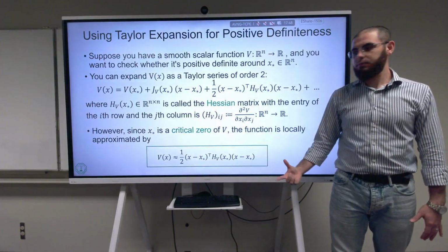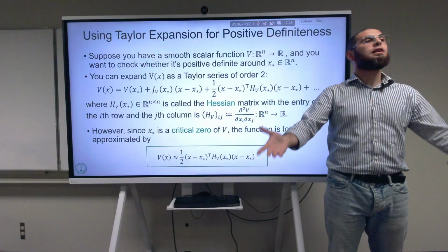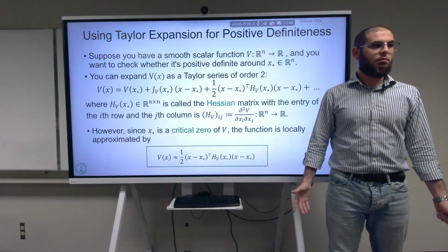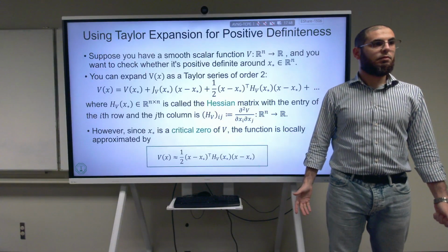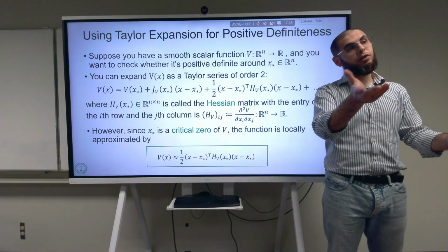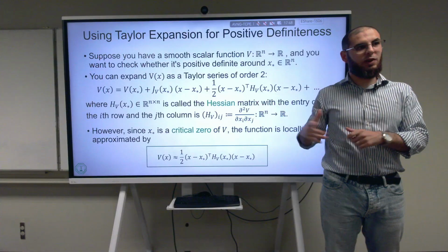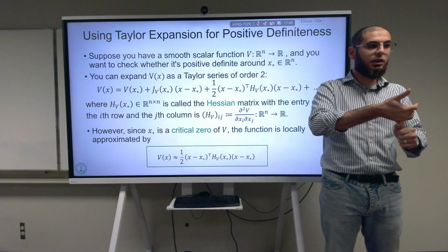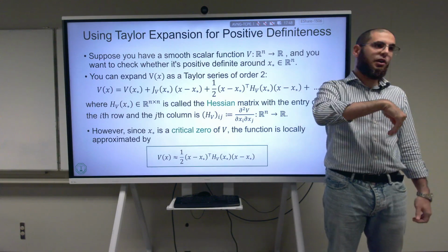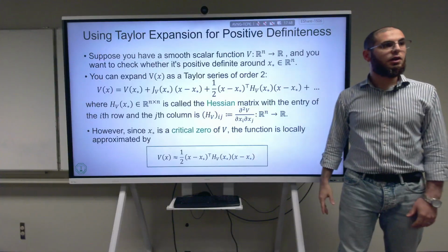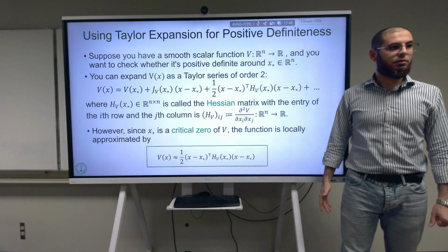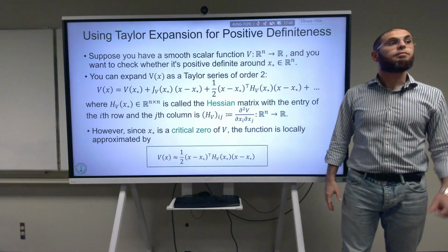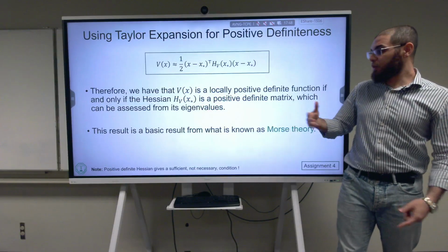What is V over here? V is the function you want to check its positive definiteness. So it is that energy-like function, or its derivative. Remember, when we do Lyapunov's method, we have to check whether V is positive definite. We have to check the definiteness of the function, but we also have to check the definiteness of its derivative. So in both cases, you always want to check the definiteness of a function. So this is sort of a shortcut for that. Absolutely. So now the conclusion, exactly.